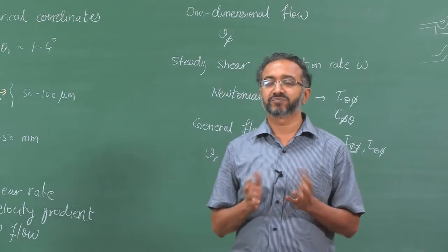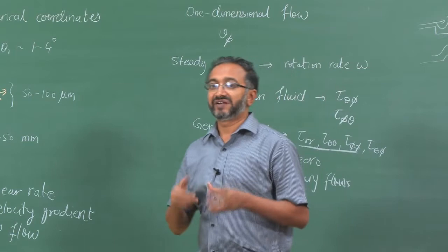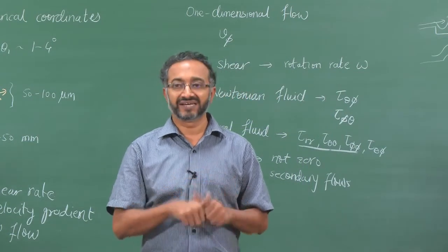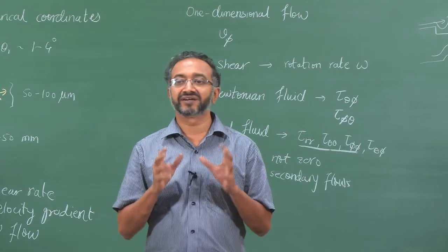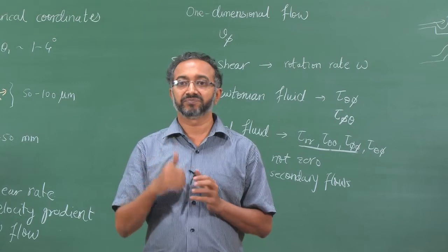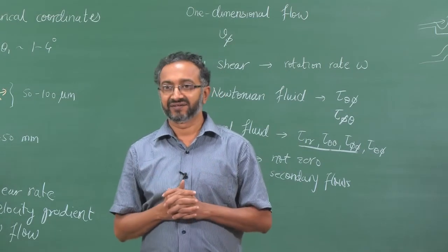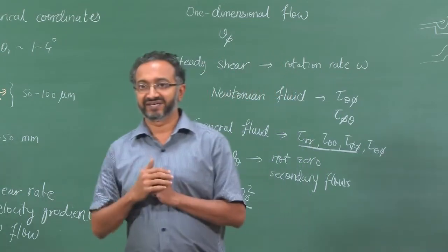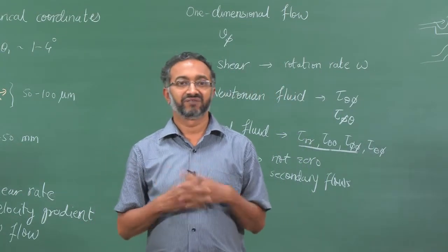One answer is that possibly the torque required will be less. In that case I will measure the viscosity to be less, and therefore there will be an error in measurement. The actual viscosity is eta, while I might measure 0.9 eta. So, will I measure 0.9 eta or will I measure 1.1 eta, that is the question, and why.